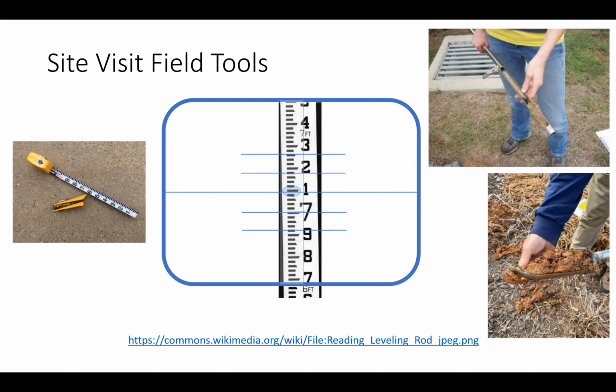You might not always use it, but it's really nice to have. Over here we have this pocket rod and hand level. This is kind of short of the accuracy you get from an actual level or a total station. But for quick readings of relative elevation, I just have to say the eyeball is so inaccurate in terms of thinking about slope and relative elevations.